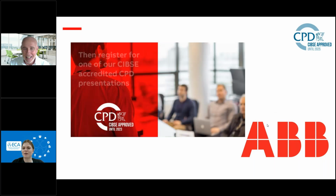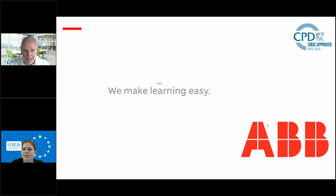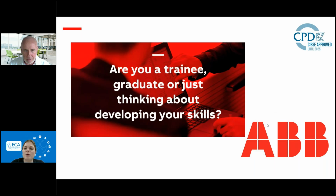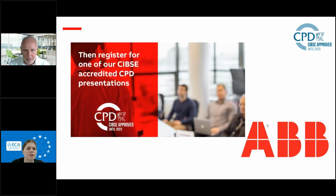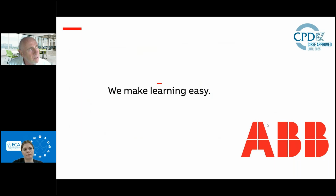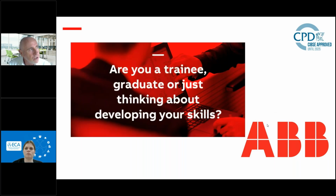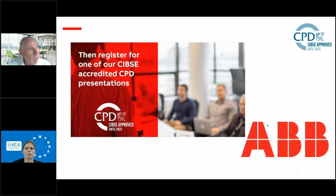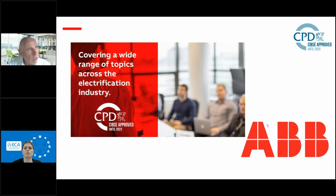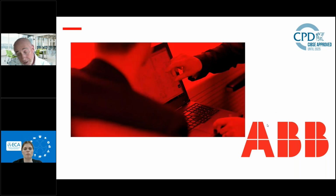Yep, so we've got another question come in. Can you clarify that you can't use MCCB on life safety systems now, and would this need to be fuses instead? For instance, within the main switchboard, putting fuses for fire lifts, etc. We normally see, in the designs that we come across and build panels to, switch fuses on the live side of the incomer, so they're not forming part of the outgoing circuits when they go off to the sprinkler motor starters and things like that.